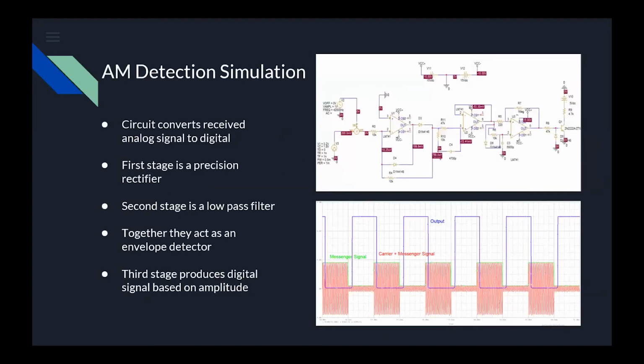Hello, everyone. My name is Shine Rafar, and I will be presenting the AM detection circuit as well as the progress made by the transmitter subteam. The purpose of the AM detection circuit is to convert the on-off keying into a digital high and low signal that is fed from the receiver. This is a key component to this design because it is directly feeding into the Arduino itself.